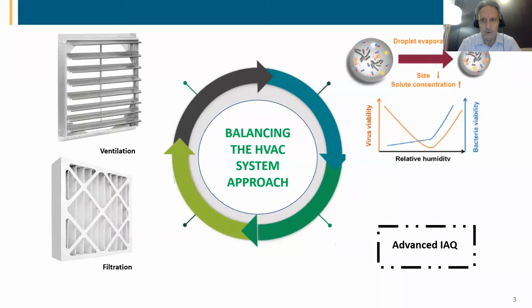In the upper right-hand corner, I portray relative humidity. We have heard a lot of late with regards to relative humidity and its impact on our physiological well-being, that 40 to 60% sweet spot that is the best for us from a standpoint of our health and well-being may also have limiting influences on certain viruses and pathogens. They live longer and they're less infective or less critical to our health at those specific humidity ranges. So 40 to 60 RH in the building, if you can do it, is a great idea as well.